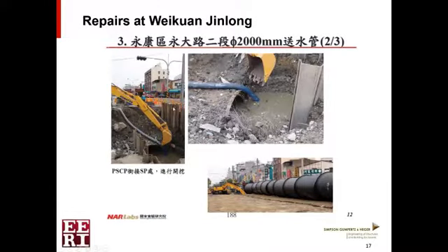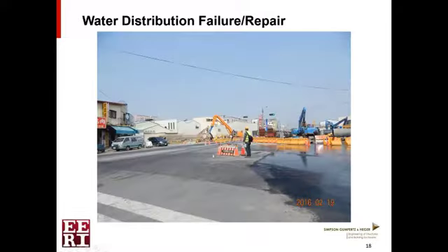You can see some sheet piles that have been installed, obviously some pumping of water to try to help with that demolition process, and the process of rerouting these major utility lines. So you can see they're quite tall, typically between 1.5 to 2 meters tall. This is what the space looked like after the demolition was completed.